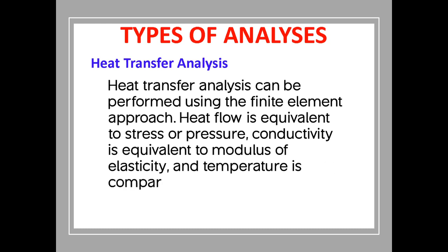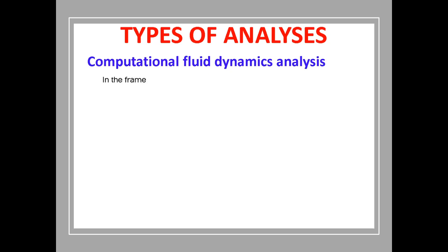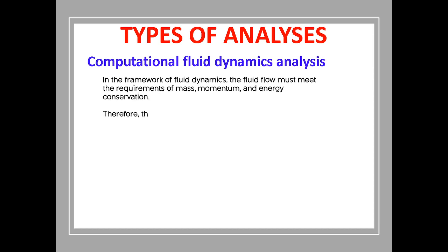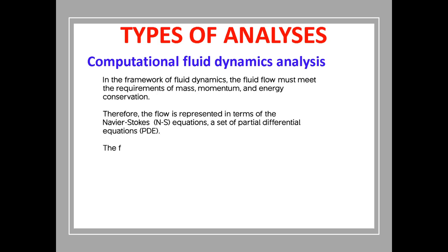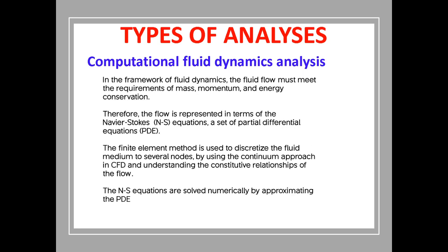In the framework of fluid dynamics, the fluid flow must meet the requirements of mass, momentum, and energy conservation. Therefore, the flow is represented in terms of the Navier-Stokes (NS) equations, a set of partial differential equations. The finite element method is used to discretize the fluid medium into several nodes, by using the continuum approach in computational fluid dynamics and understanding the constitutive relationship of the flow. The Navier-Stokes equations for the continuum are solved numerically by approximating the partial differential equations through a sequence of algebraic equations that the computer solves by adding pertinent boundary and initial conditions.